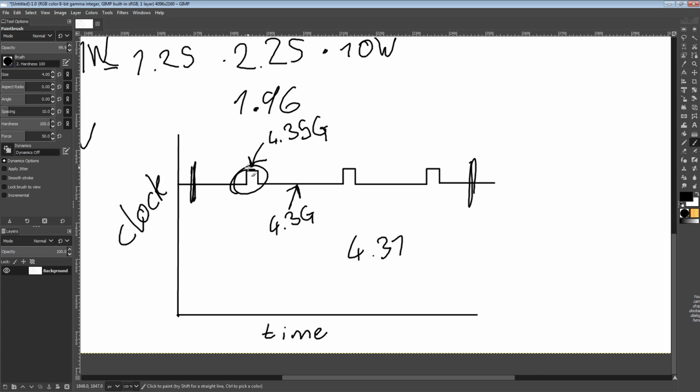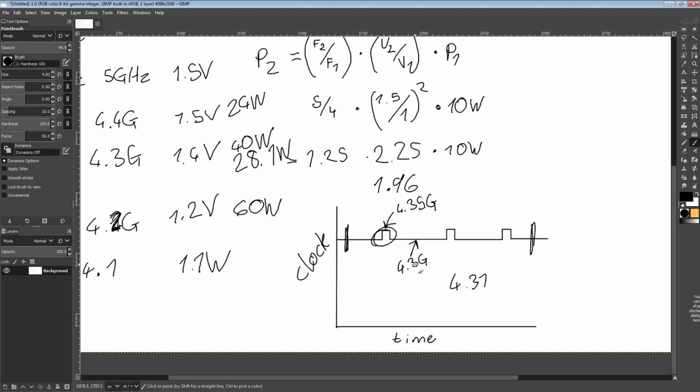It's not going to crash the chip at stock, but if you start overclocking with BCLK, this little nub of frequency is going to go from being 4.35 gigahertz to say 4.5, when your chip is only stable up to 4.45 on single core workloads. And that's what I really hate about it: this restricts your maximum average frequency, which I think is a silly design flaw of the algorithm.